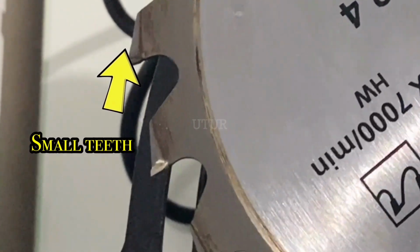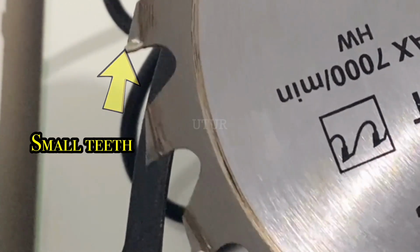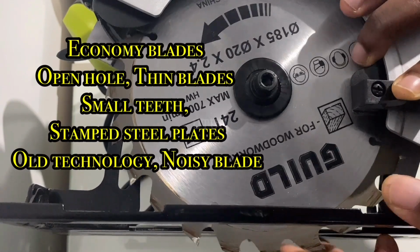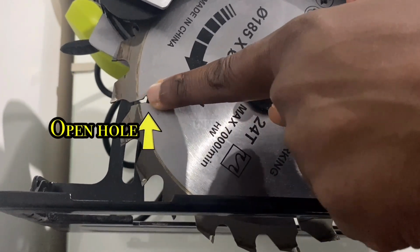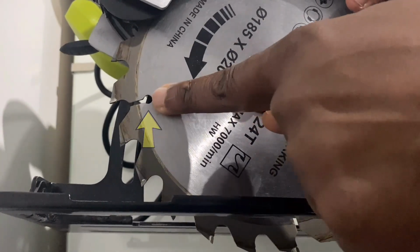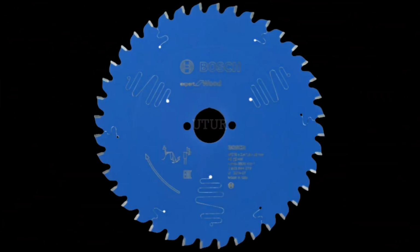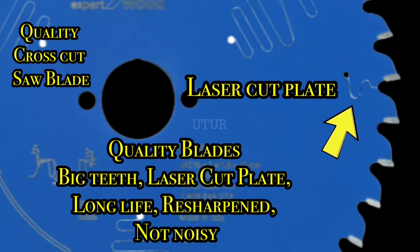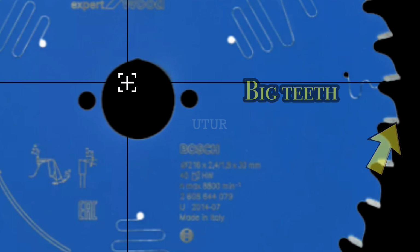Economy blades almost always have a thin stamped steel plate with expansion slots that end bluntly in open holes, which is what we've got here. The open hole exudes or signals old technology and a noisy blade, whereas good quality blades have a laser cut plate, as you can see here, and the length and width of each tooth tip is bigger.